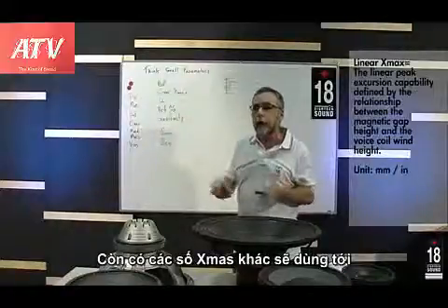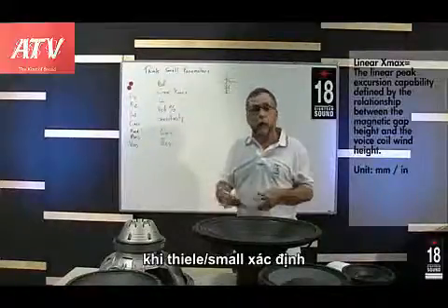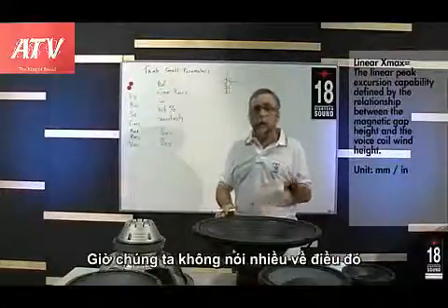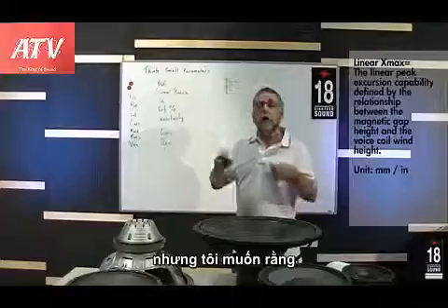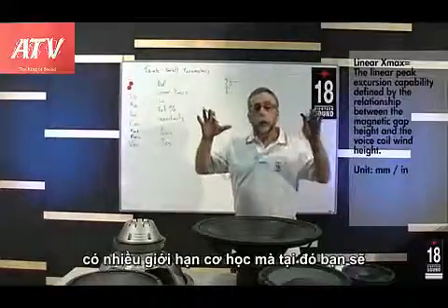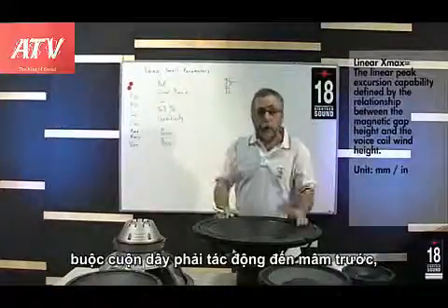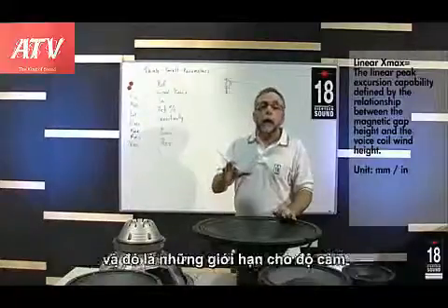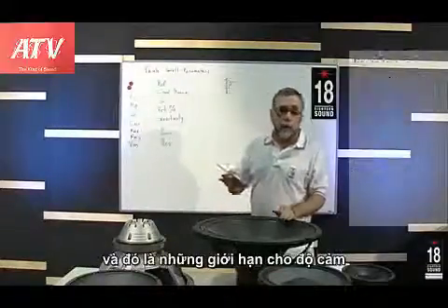There are other Xmax numbers that have come into play since Thiele and Small defined the original Thiele-Small parameters. So I won't talk much about them now, but I do want to say there are mechanical limits, where the coil would strike the back plate or the suspension cannot move any further. And there is an inductance limit.